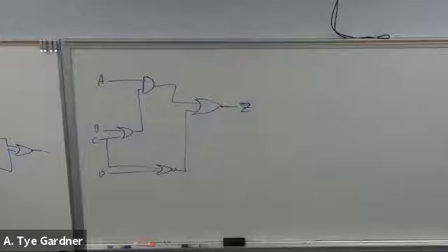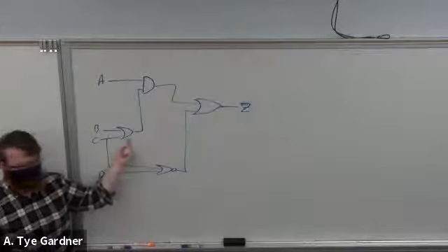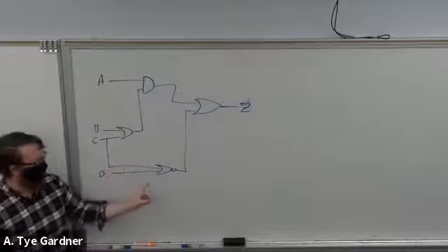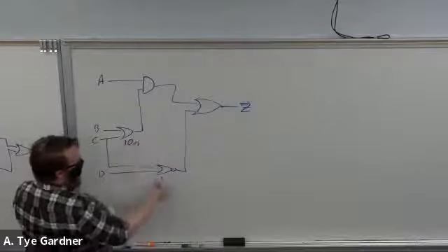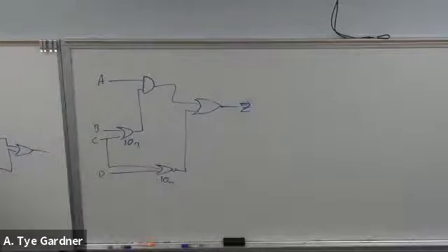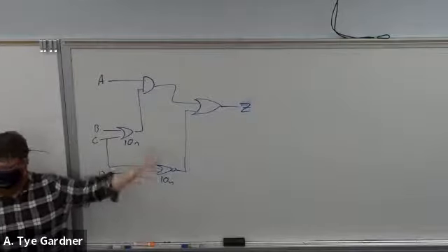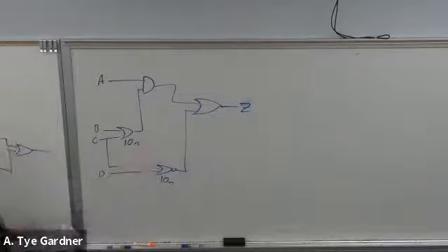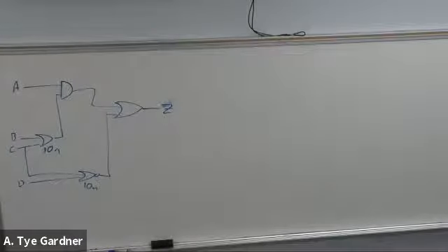Now, I won't, but I could. I just want you to understand that it could be different, right? Because a NOR gate has a longer delay than an OR gate. It just does because it takes more gates to make that, more transistors. I'm going to be easy on you and say they're all 10 nano, most likely. They're all the same. But be aware that you could have two paths that have different numbers of gates but have the same delay, or something weird. I'm not going to do that, but it could happen. Okay, make sure I can get all of this in the window. So that means that C is our risk.